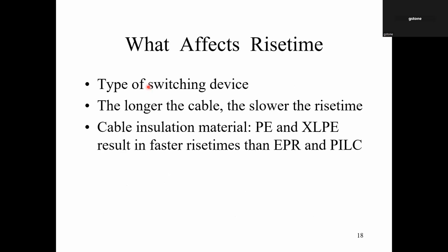Okay, but there's rise time, and you'll see why rise time is going to be important in a few more minutes. Usually the shorter the rise time, the more danger it is to the winding. I'm sorry if you don't know that, I'll be talking about it in a few seconds. It turns out that if you have a longer cable, the rise time will gradually slow down.